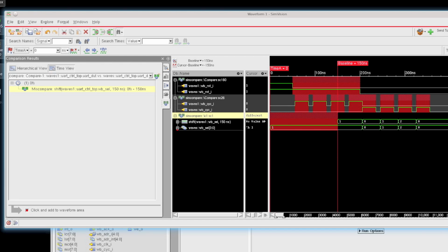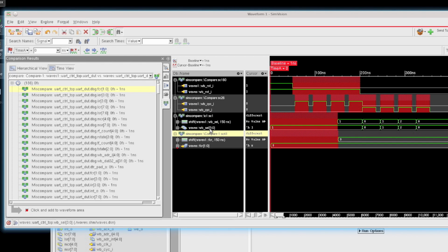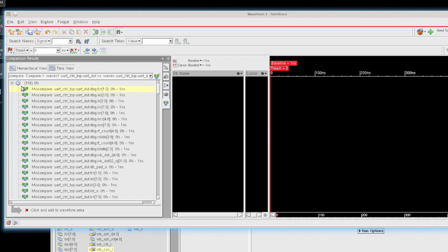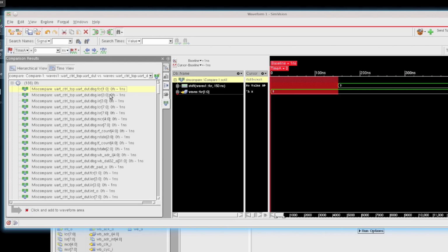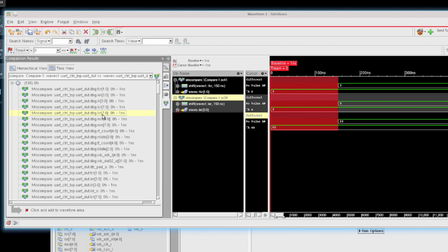So I'm going to send these results out now to the SimCompare Manager. And again, I'm going to select all and just clear this out. And I'm going to take a look now at where the issues might be. And it looks as though there's a lot of startup condition problems. At 0 seconds, there's differences. And this might make sense, right? Because if we shift out reset, then sure, the data that we're sending from our UVCs might actually be affected.